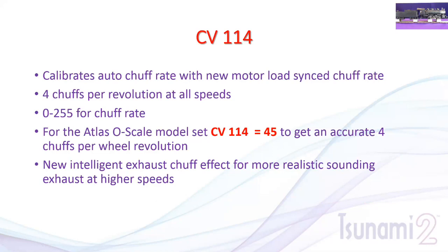But now with the upgraded motor control technology and the back EMF algorithms, we're able to identify the rotations of a motor. And so when you set CV114, we're actually going to adjust the chuff rate based on the rotations of the motor. So when the motor stops, the chuff doesn't continue because the motor isn't rolling.